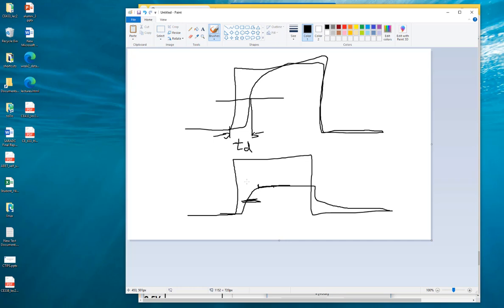Does it matter? You want to find the time, right, to compare to the 50% voltage time here, so you can define that time delay, right? So it doesn't matter where you define the time for the voltage for the input rising edge, like 50%, 25%, or somewhere else.